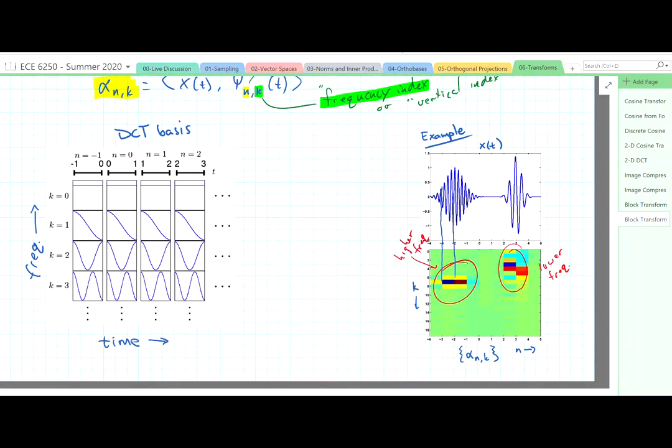But if we perturb any of the coefficients, then at these boundaries, at these integer boundaries, the signals that are built up in their separate integer cells won't match at the boundaries. And when you look at an image that's that way, you can see the blockiness.